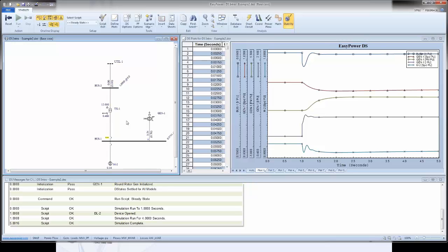One question that we don't answer here is what happens if there is a transient event in your system. If you run a load flow, you would never know the transient states that the system goes through, meaning you might have a voltage overshoot, a voltage dip, a voltage oscillation, an unstable situation, all different transient events that load flow doesn't cover. It wasn't even designed for that. Load flow was designed to give you the steady state results of the system, and that's exactly what it does. When you use that tool, you always have to ask yourself whether this is what you really want to do.